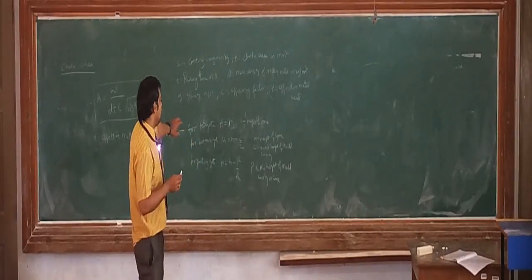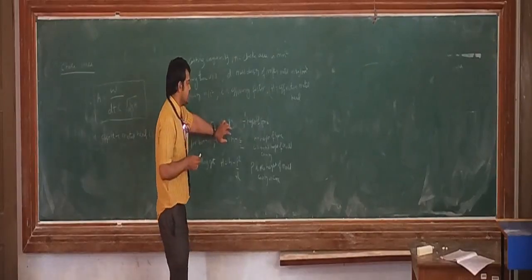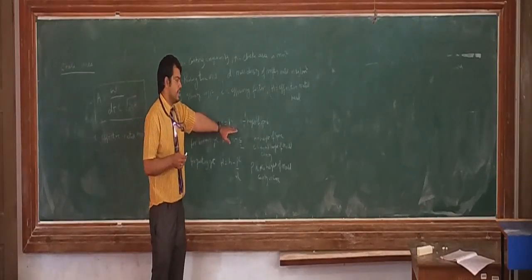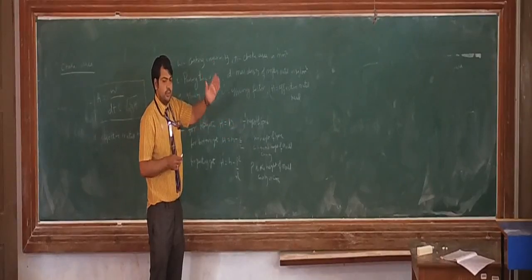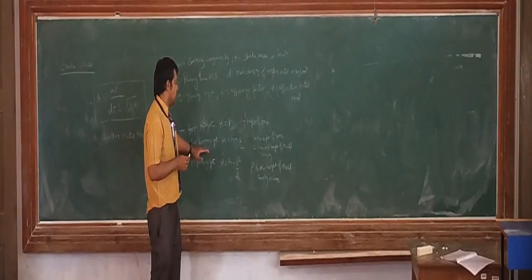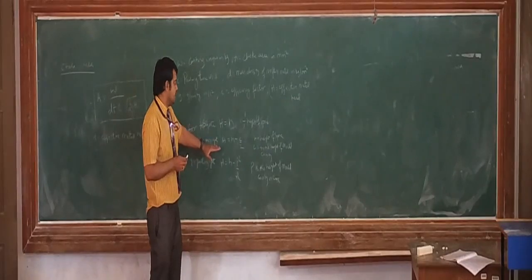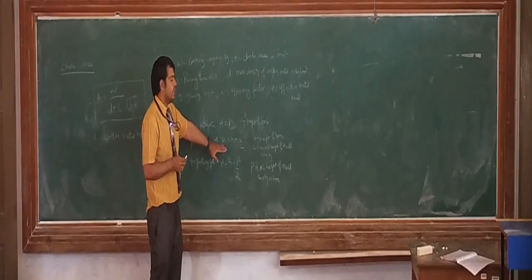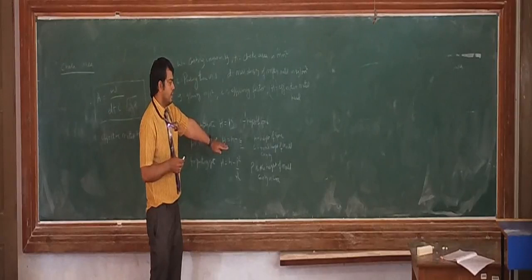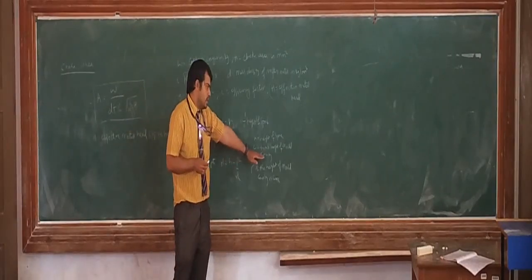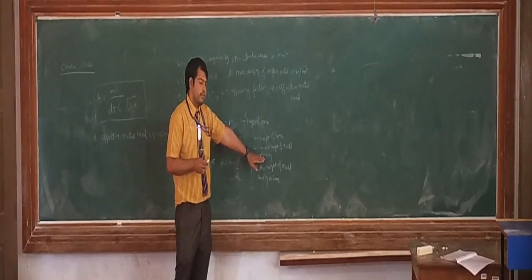So there, how we are going to find this effective metal head is H is equal to small h, that is height of the sprue, okay, through where the metal is coming. For bottom gate, that is the gating system where the runners and other parts of the gating system are situated below the parting line, those are called as bottom gate, and here H, that is effective metal head, will be equal to H minus C by 2. Okay, what is C over here? C is total height of the mold cavity.